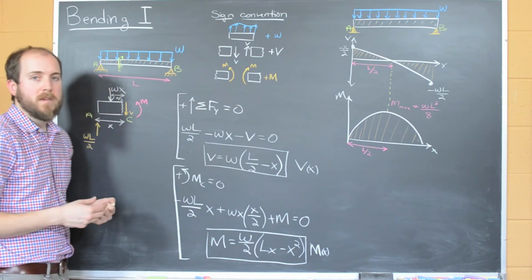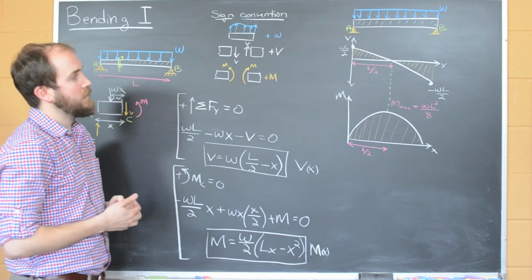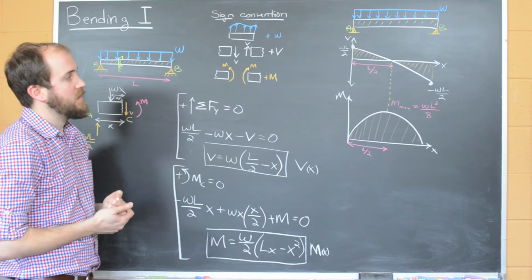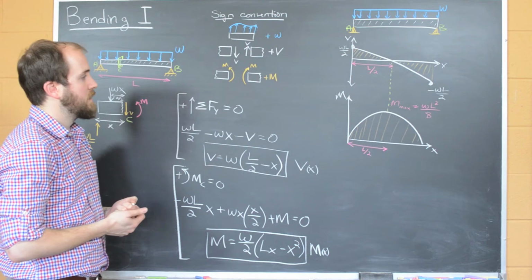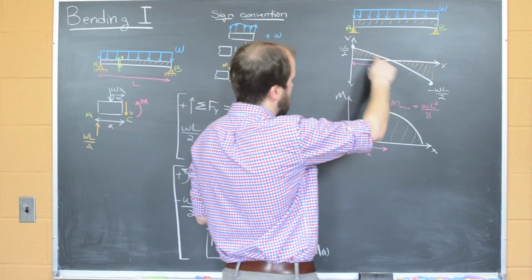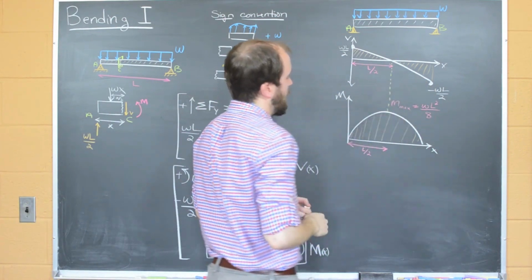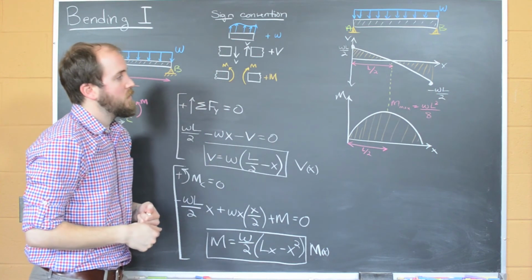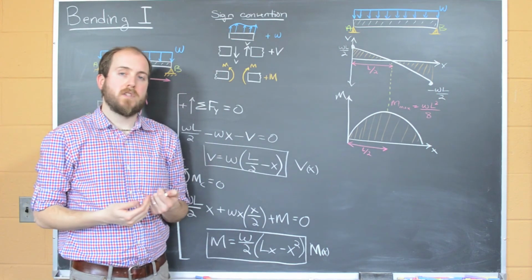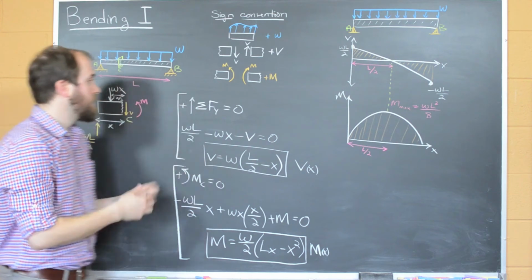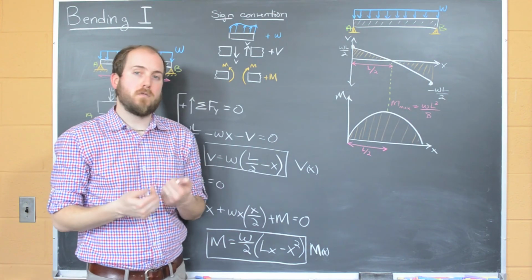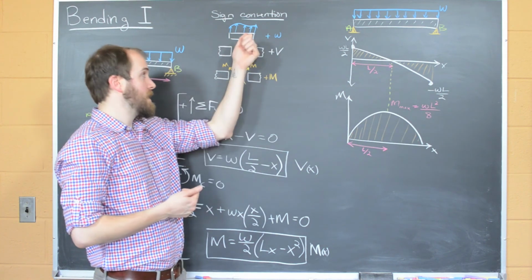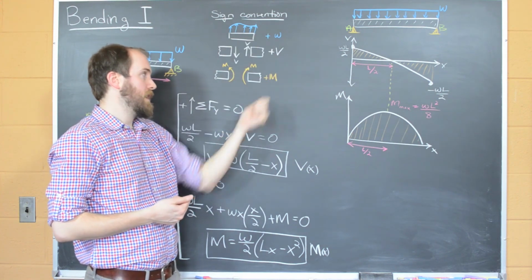And so you'll work through some exercises where you can do this for a variety of different loadings and different boundary conditions. And what we'll end up doing in our next lesson is really exploring this relationship between this curve here and this moment curve. And we'll go about a different way of approaching these same shear and moment diagrams. Instead of using a free body analysis, we can use some differential relations between the load W, the shear force V, and the moment M.